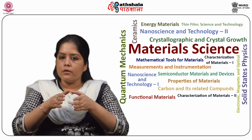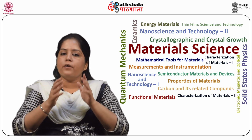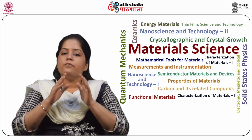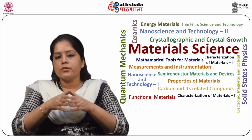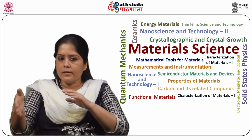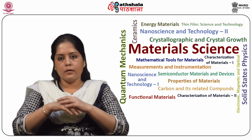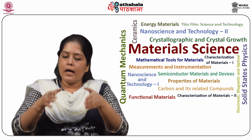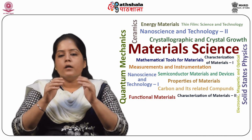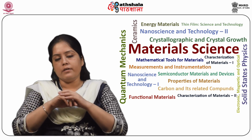The basic construction of the most common ultrasonic motor consists of a high frequency power supply, a vibrator, and a slider. The vibrator is composed of a piezoelectric driving component and an elastic vibratory part, and the slider is composed of an elastic moving part and a friction coat. So the piezoelectric material having high mechanical quality factor is used in ultrasonic motors. Ultrasonic motors are driven in two ways: step drivers and direct drivers.